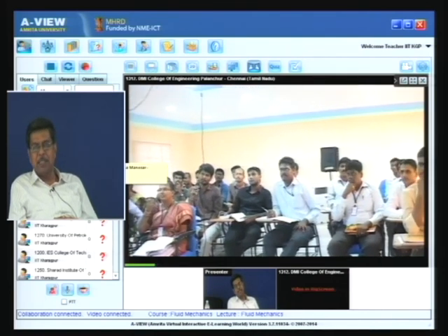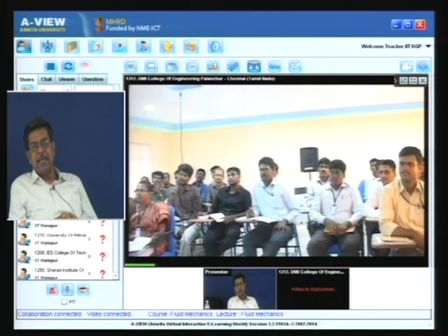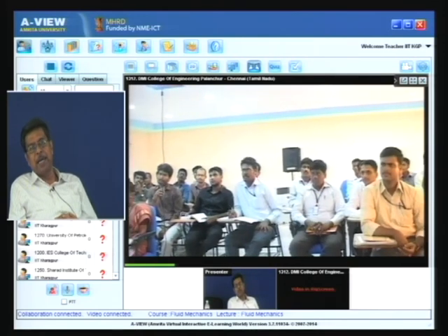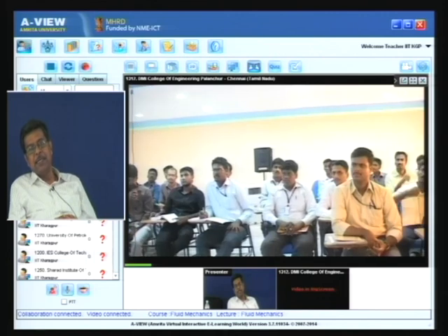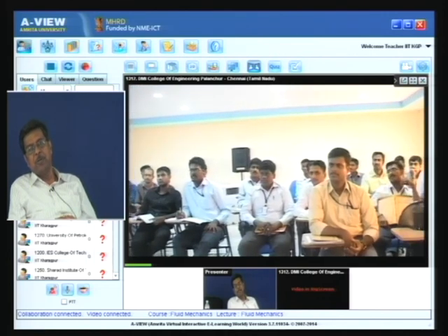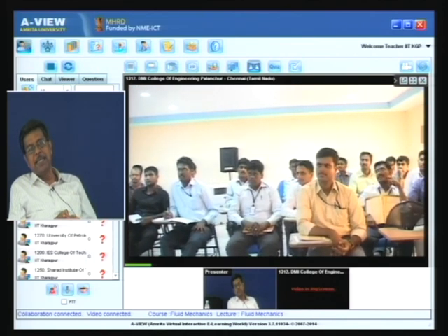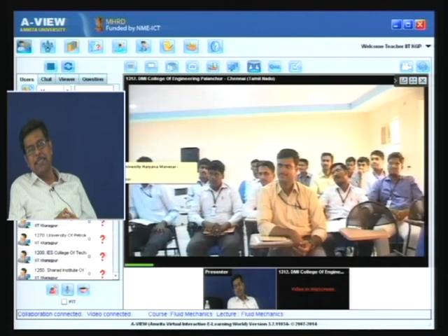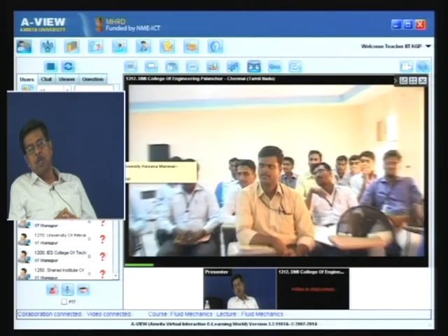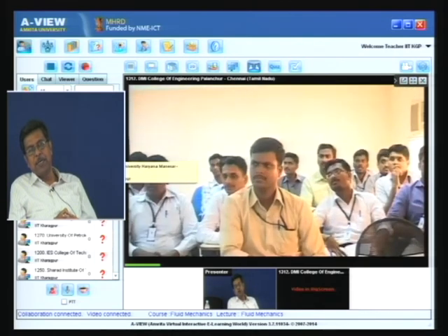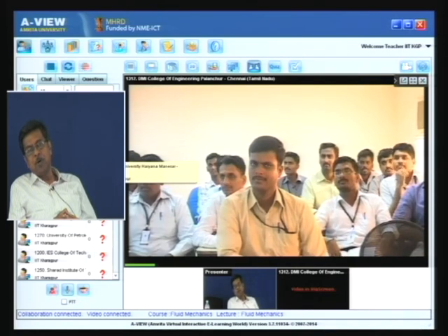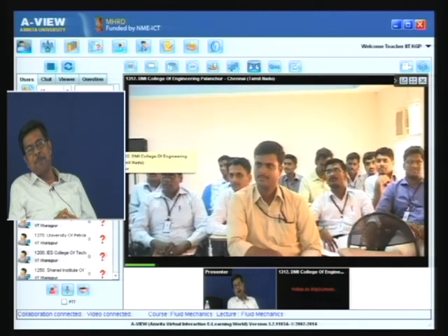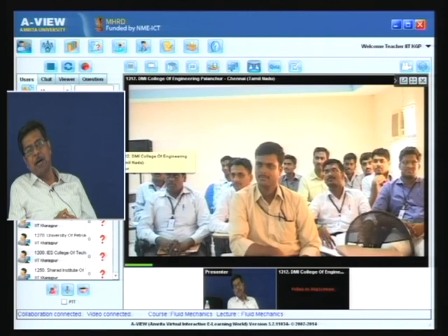Again I tell, just now I have explained this, that in a jet engine, if you take a control volume of the jet engine, air is coming into the control volume, because a jet engine takes air in from the ambient, and the products of gases, that means the jet, goes out. So you have to consider both inflow momentum and outflow momentum. In case of mass, you have to consider the inflow mass and the outflow mass.